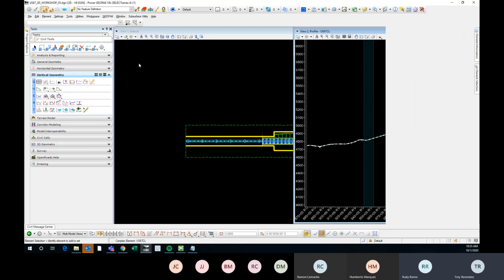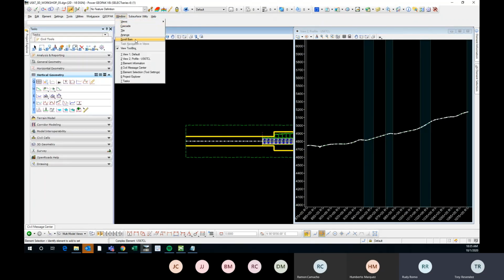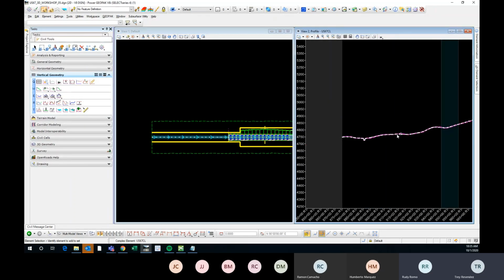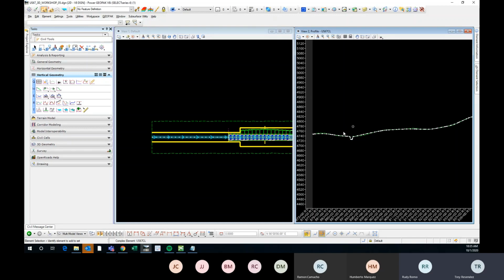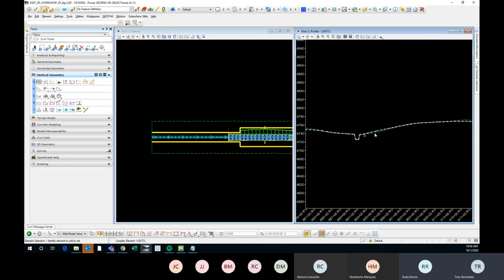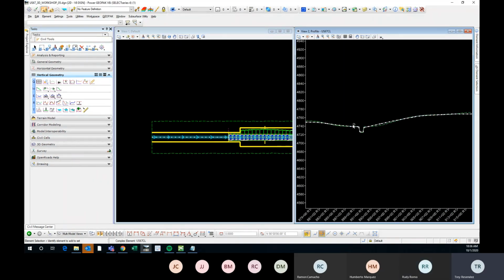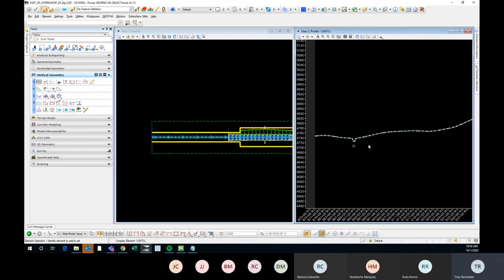and there's a cool function that they have. It's project profile to element. What I usually use this for is if I'm trying to see the right of way in my profile view, because sometimes it's useful to be able to see what's happening on both sides of the right of way relative to your center line.